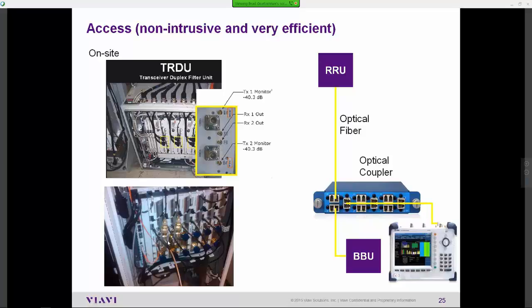Some I have great admiration for came up with, no, I need to have, and oftentimes I carry with me, low loss pass-through couplers that allow me to leave that antenna in service while I'm otherwise monitoring and looking at transmit quality off that 40 dB on test point.